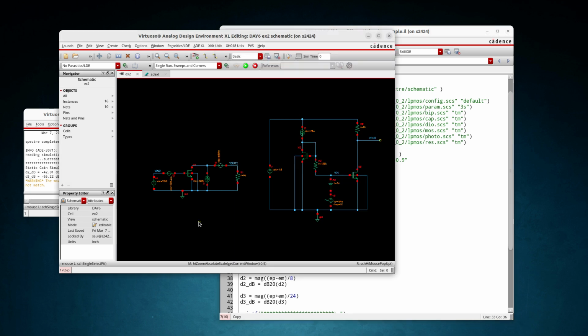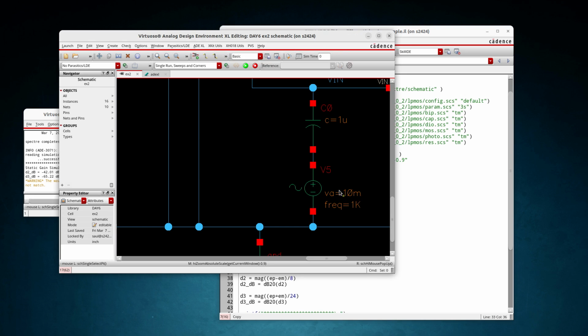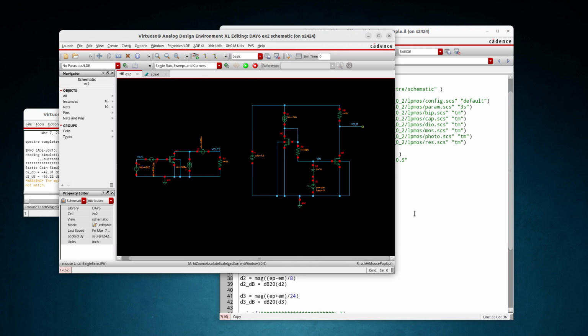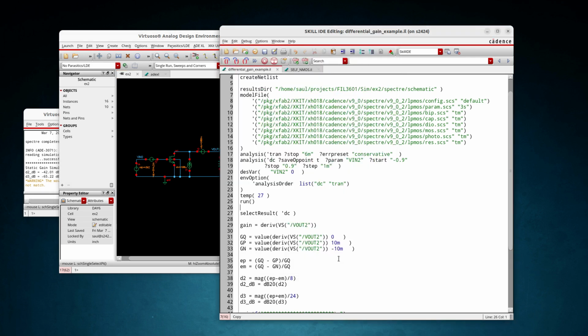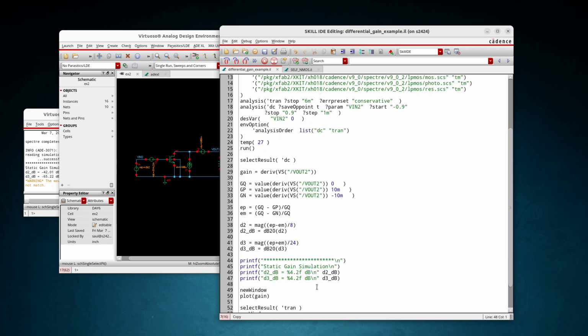This is under the assumption that I will inject a signal with 10 millivolt amplitude. So I will start checking what the error is if I move to a maximum amplitude of plus minus 10. And I calculate these errors, and then I can immediately calculate the second order distortion and the third order distortion also, and just present the results.